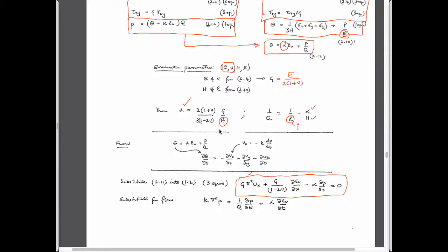And the other relationship we have is continuity. Continuity of volume or continuity of mass. It's written in terms of volume in this particular case because these are velocities rather than products of velocities and densities. And so if we throw Darcy's law into this, this is just the change in volume strain with unit time of the system. And so it's the amount of fluid source volume that goes into or out of the system by both fluid pressure effects and by strain effects.